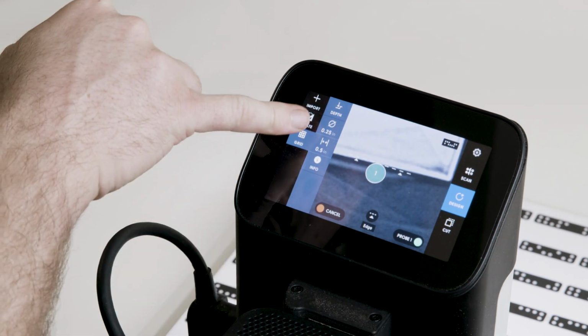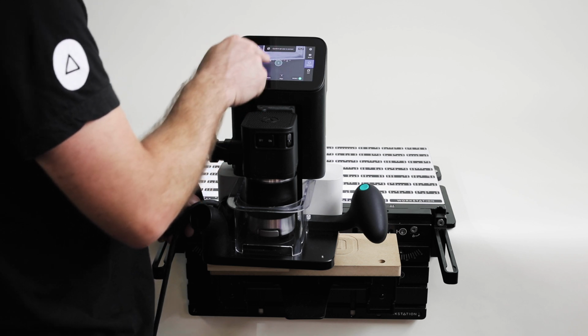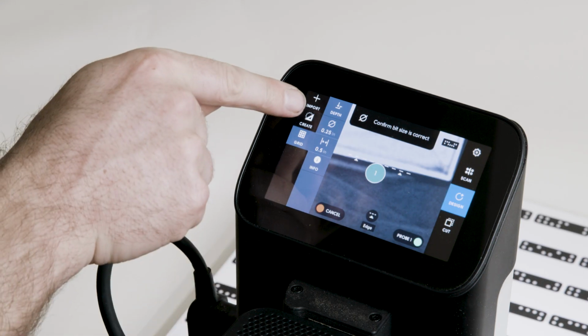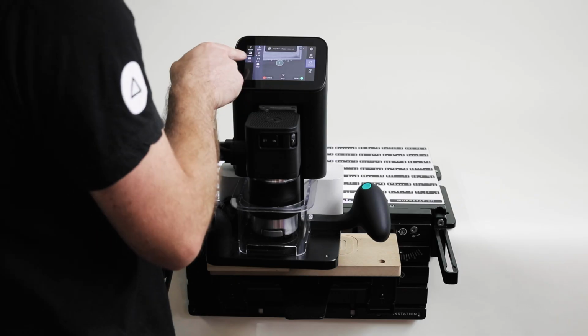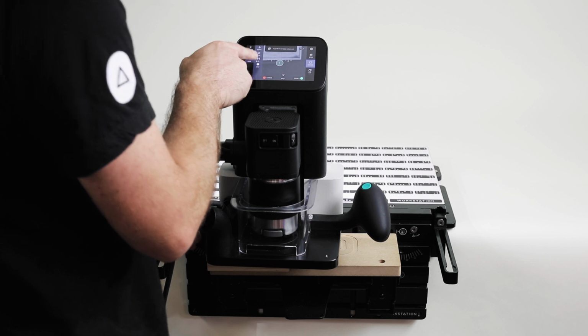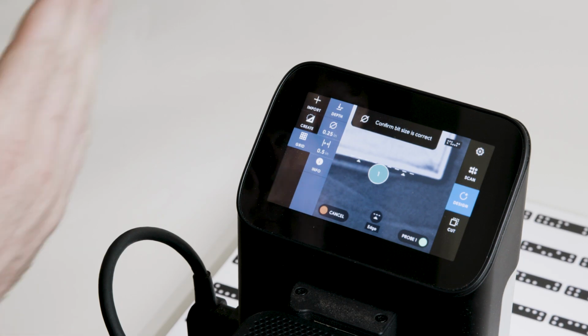Then I'm going to quickly check the diameter of my cutter. That's represented on screen here. So this is a 1/4 inch cutter. Note if this is set to 1/2 inch, it'll be really large and you'll get inaccurate readings. It'll be offset. And then check the increments. So this is just the spacing dimension between grid increment lines.